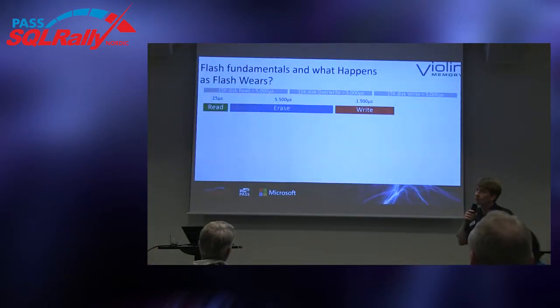So a little education in what flash is good for, what it is not good for. Flash is very good at doing reads. But then there's a problem. You cannot overwrite data in flash. You have to clean up first, do erases, and then you can do writes. That process is called garbage collection. Everybody has to do it inside the flash system.